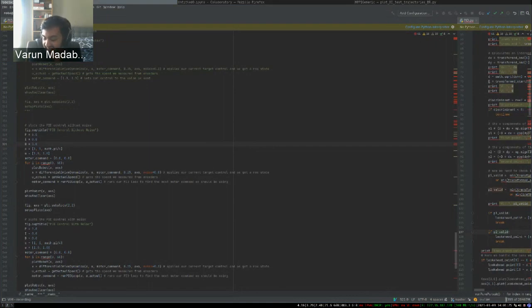Generally, that's not so safe to do because you don't want something automatically controlling the robot. There are various system identification tools that you can look into, which will extract some characteristics of the robot. But to put it simply, it's usually easier to hand tune the PIDs than to automate it. I don't know if, Jason, you have a different answer. No, I agree with that.